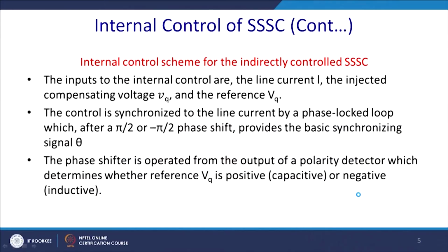So, let us discuss the internal control scheme for the indirectly controlled SSSC. The inputs are, please note, the line current, the injected compensating voltage Vq and the reference Vq star, or Vq reference. The control is synchronized with the line current by a PLL or phase lock loop.